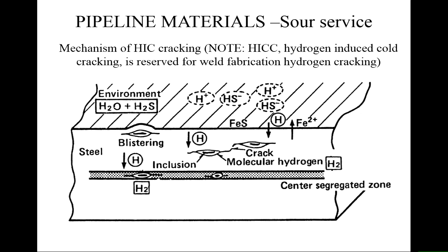Now, for a long time, it was thought that hydrogen just collected in these cracks and defects and opened the defects up and made the defects more susceptible to cracking. And there is a good part of hydrogen-induced cracking which is due to that mechanism. But if you just take a piece of steel with no defects in, a perfect piece of steel, and you charge it with hydrogen, by whatever method you like to use, electrochemical methods, and you measure the fracture energy, you will find that hydrogen reduces the fracture energy of steel.